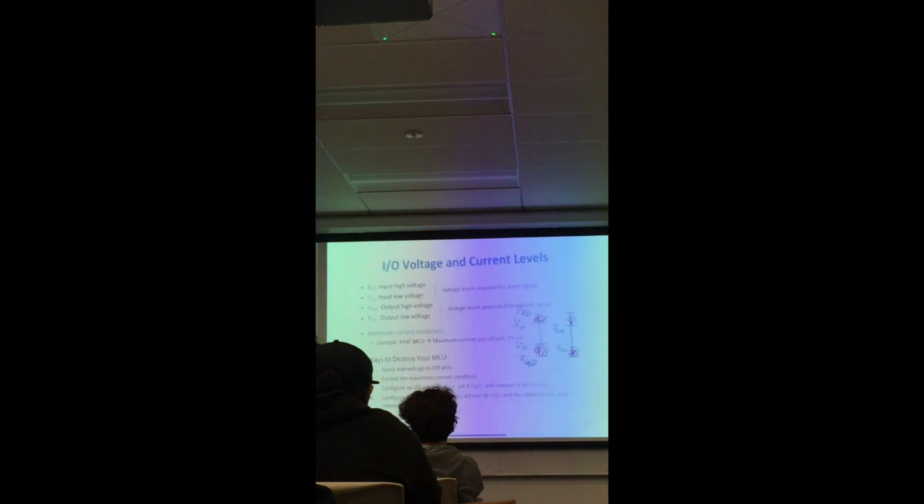And overall, all pins together cannot supply or source or sink more than 100 milliamps of current. Otherwise, you will fry the micro. First, you will fry the pin and anything connected to it, but maybe you will damage the whole microcontroller.